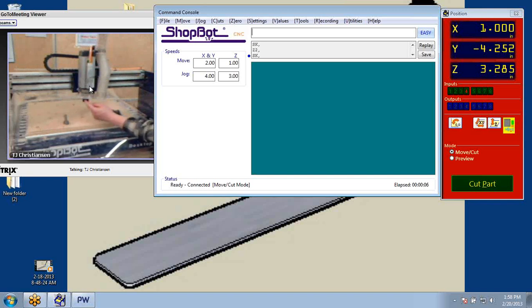Anytime you have a collet like this, you want to pull the thing off, blow the sawdust out of it, and pull it apart. If you have a spindle, your collet is actually a spring collet. See how I just sprung that apart? These two pieces have to come apart here. This is where you tap them out, blow them out with a little air, and get all the dust out of there.